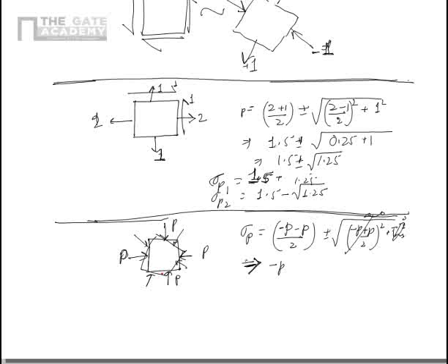So the two extremes are: one condition in which we have a pure shear condition, in which the transformation makes the shear go away and become 0, and only two equal and opposite normal principal stresses occur. But in the other condition, a pure normal condition, in which the applied loads are equal normal stresses acting in the same direction, transformation doesn't change anything, which means the stress state remains the same to whatever angle you transform to.